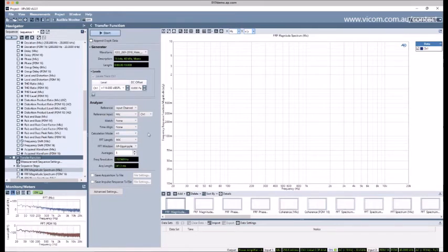Calculation mode, that's a setting where I'll just say that unless you know what it means, just leave it alone. I'll use a 48K FFT. That will give me a frequency resolution of 1 Hertz. And this is a 10-second long signal, and it's non-repetitive, so I want to capture the entire signal.